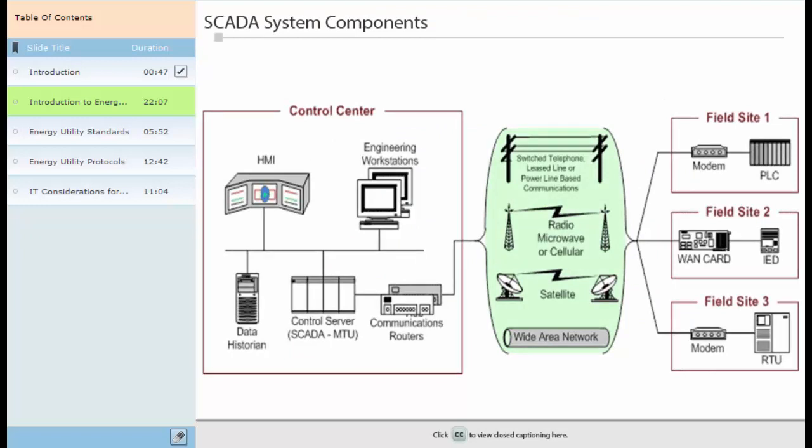Supervisory control and data acquisition, or SCADA, systems gather real-time data from the electrical grid, ensuring system reliability. Functioning as a supervisory solution, SCADA monitors the grid from a remote location. SCADA files recorded events to a specified location while monitoring process conditions. If a potential hazard is detected, like an imminent outage, an alarm is sounded. SCADA subsystems connected to the network provide an additional level of control.